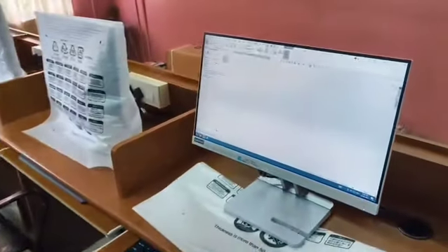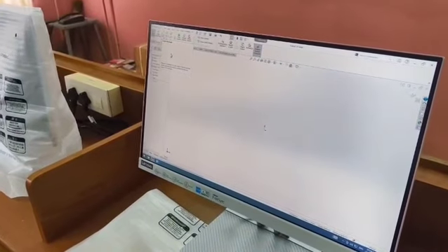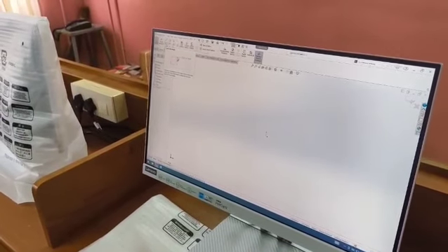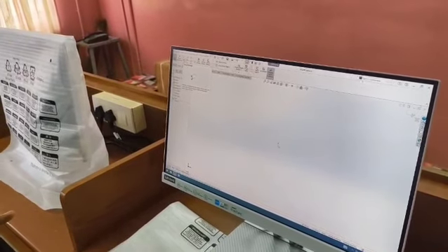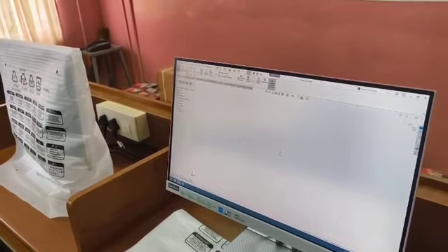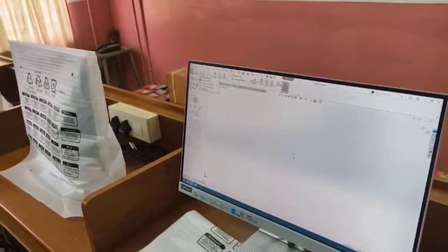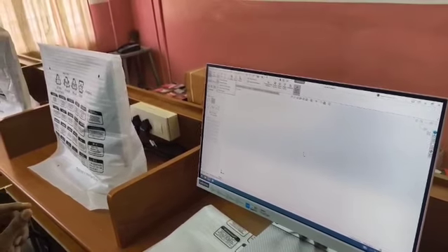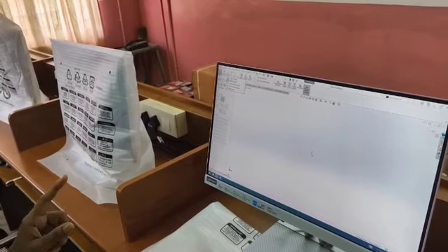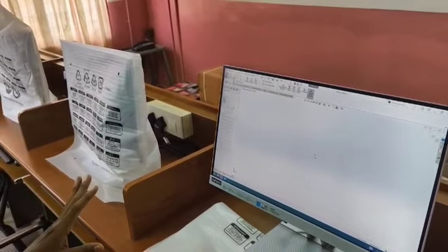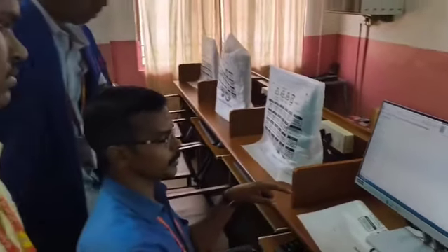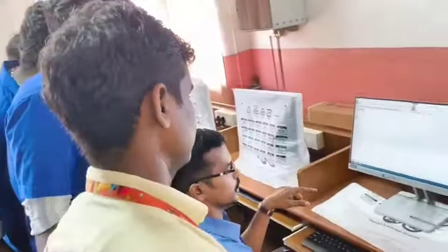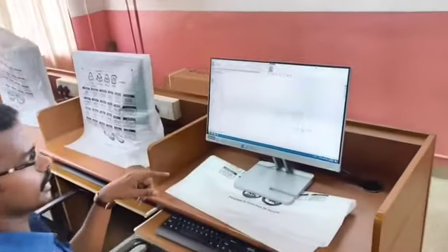For drawing the object, now I will just draw a cube shape like that. So I will select the rectangle tool. Actually in the rectangle itself you have many options. I can select center rectangle, or we can select corner rectangle also. I will select corner rectangle. Corner rectangle means you have to pick 2 points. So I am selecting this point as the first point and this point as the second point.